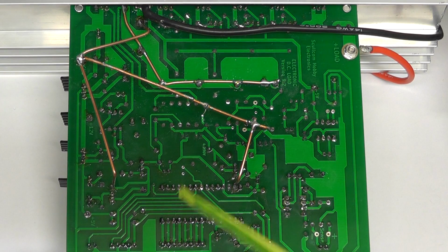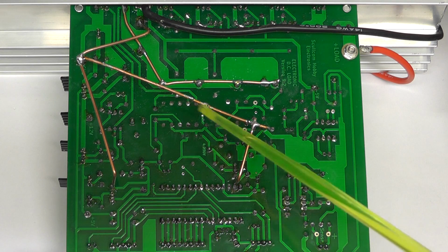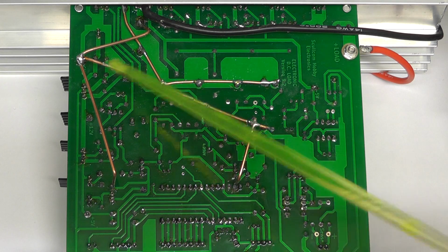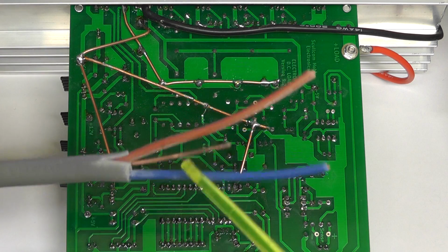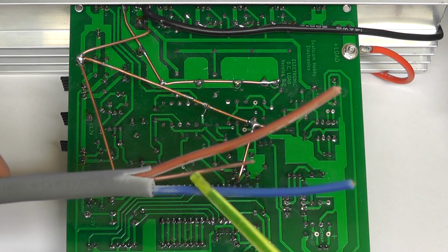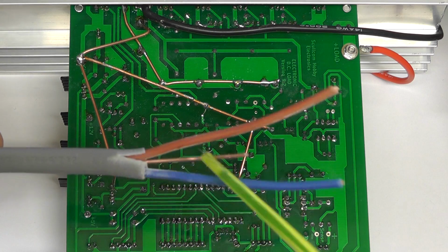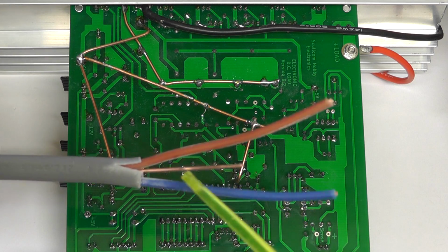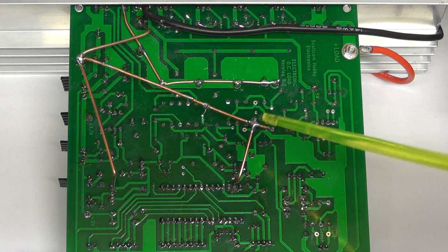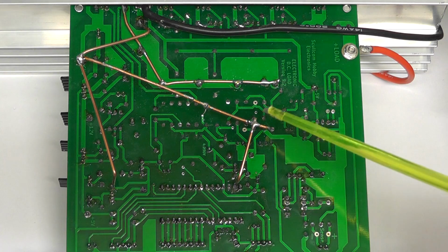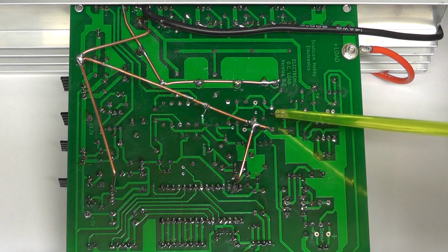Here we now see the additional earthing that I've added on the underside of the printed circuit board, this heavy gauge copper wire, and I simply used some wire I stripped out of some household wiring cable, taking the earthing strip out. It's around about 14 gauge wire, but any heavy duty copper wire would do for this purpose. So what we've done is we've anchored the copper wire there. I've raised it off the print so it's not shorting anything else out, and we've anchored the copper wire in